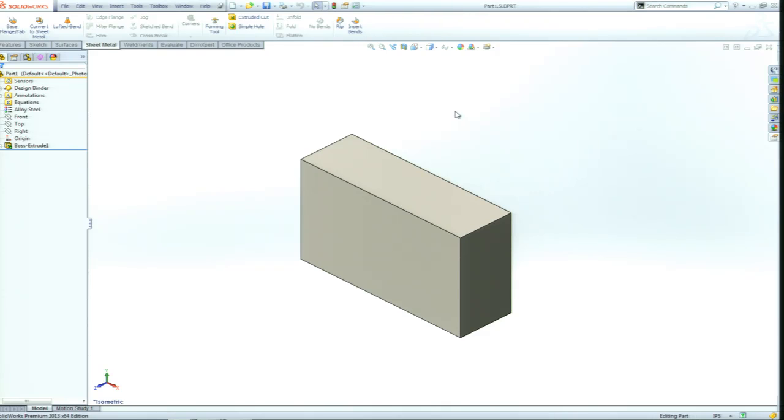So all this part's going to be on this size paper, and you guesstimate, because you don't know, sometimes a large assembly is a little bit bigger when you start trying to put the views in, now I got to reduce the scale to get it to fit. Then you got to manually go back to the part, open it up, change the scale. Is there a way just to leave the scale generic on the part, and when you scale it in, it plugs that information in from the sheet scale that it's actually...